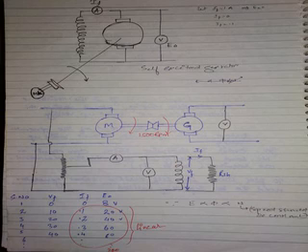Plot a tangent to OCC. So this is normal. You will plot OCC, you will plot the shunt field resistance line. These two you will normally be doing first. Next, you have to plot a tangent to OCC, which is nothing but the critical field resistance line.